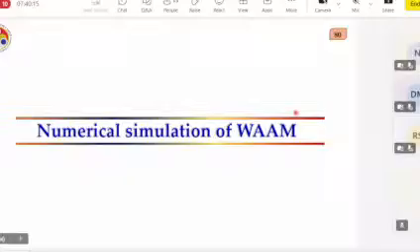And since it's a virtual environment, it doesn't know where the part is. For the software, it's like it's in the air, or floating in space. So to tell it that it's lying on the welding bed, or welding table, we need to put certain boundary conditions. For one, we can define another material over here and define the properties of the bottom plate as the properties of the welding bed.